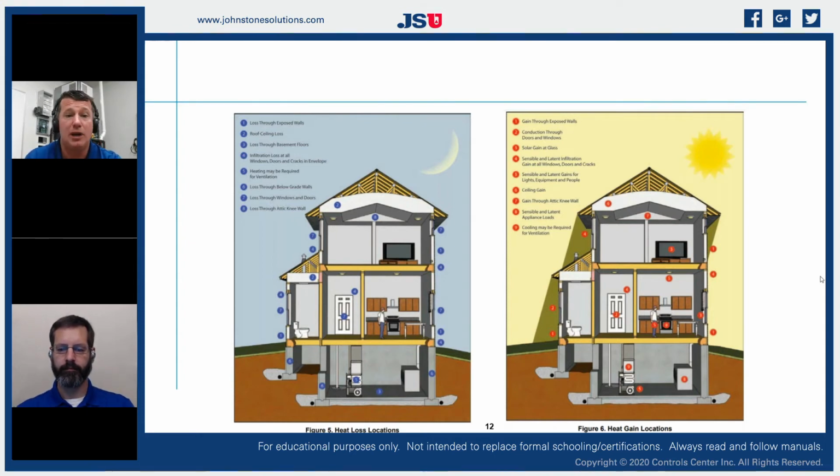If I'm talking about an 80% gas furnace, I have a draft system that is venting straight outside. So any air that is moving through my draft is now going to be infiltrated from my windows, doors, and cracks in my structure. So I have an additional load. We have a lot more computers in our structures today than we had 50 years ago. We have a lot more devices that need to be charged, like cell phones. So we have a difference in load, and we have to understand what that load is on our structure.